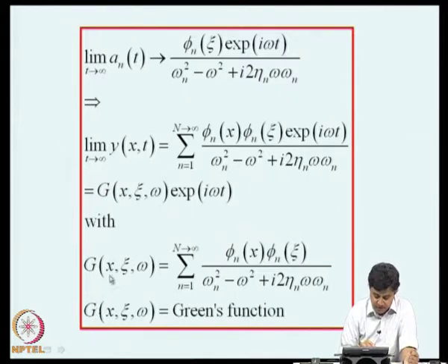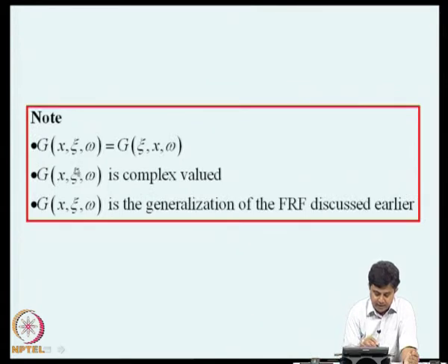It is a function of the point where you are measuring the response, the point where you are driving, and the driving frequency. It is a complex valued quantity, it has an amplitude and a phase, and it is actually symmetric in x and psi. This is actually a manifestation of the reciprocity theorem. The Green's function is symmetric in x and psi.